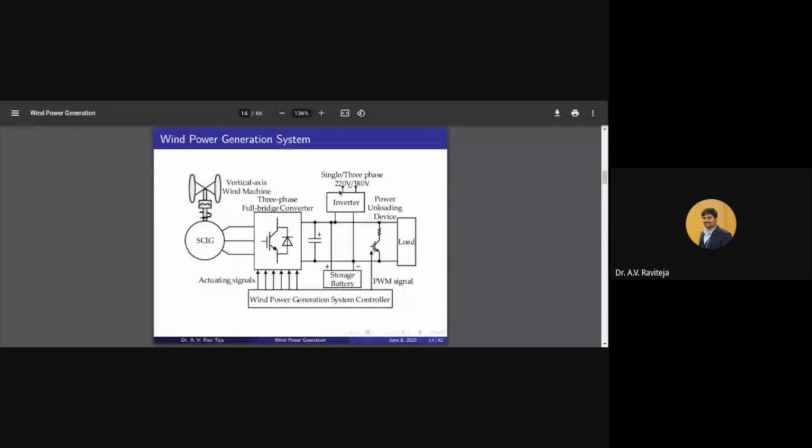So once we generate fixed voltage, this inverter has to be closed loop controlled. It is not controlled in open loop because this DC voltage will be varying depending on the voltage at the input. So I have a varied voltage, and I want a fixed voltage. So I need a controlled converter. This controlled converter will make a fixed voltage, fixed frequency supply that I can connect either to the grid or to the AC loads.